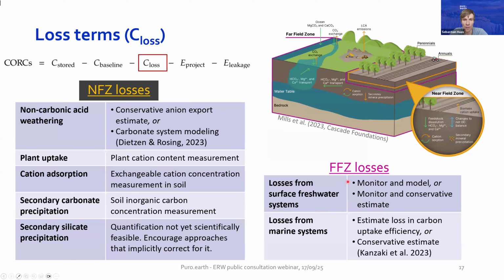The rule for the river losses has become fairly elaborate, where we require a small amount of monitoring from nearby rivers if the data don't already exist in databases, especially for pH and the saturation index for calcite, to monitor for the risk of carbonate mineral precipitation or carbonate system shifts potentially resulting in CO2 outgassing. Based on the risk assessed by this monitoring, we would require different stages of modeling these losses or different types of conservative estimate based on these risks.